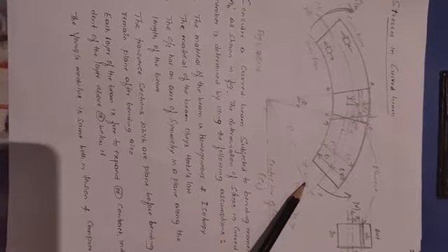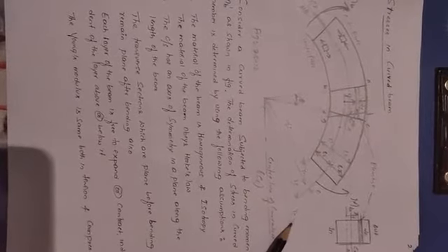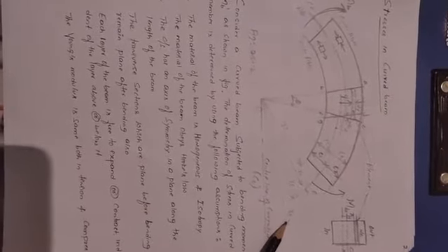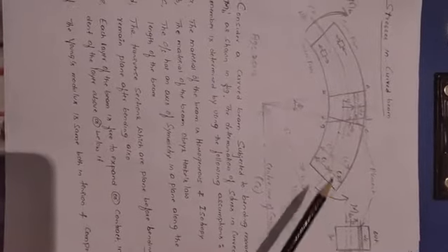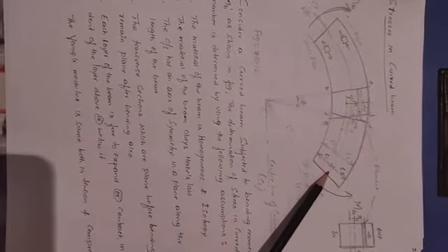Before going to derive it, first you should know the notation. R stands for radius, Ri stands for the inner radius of the curved beam. Next, Rn stands for the radius of the neutral axis of the beam. Then Rc stands for the radius of the central axis of the curved beam. R0 stands for the radius of the outer fiber. Then with respect to the central axis, we'll call it C1 and C2. C1 is related to the inner fiber, C2 is related to the outer fiber with respect to the central axis.